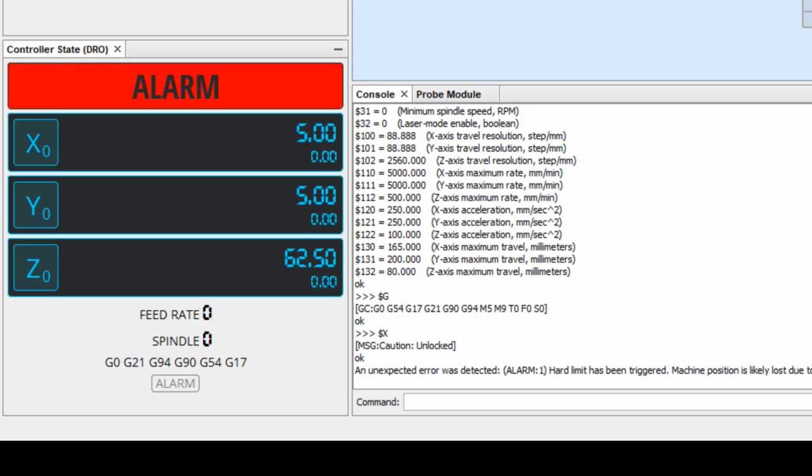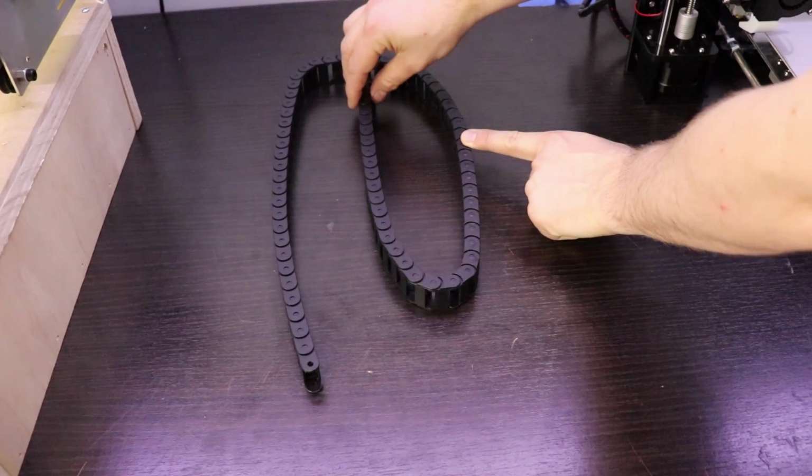The problem was so bad before that I was actually getting noise on the limit switch wires that was causing false positive readings on the limit switches, even though they weren't even being closed. Using shielded wire and connecting that shielding to ground significantly reduces the electromagnetic noise seen on that wire and pretty much eliminated all of the false positive triggers I was getting. Now that the wiring is complete, it's time to get them under control.